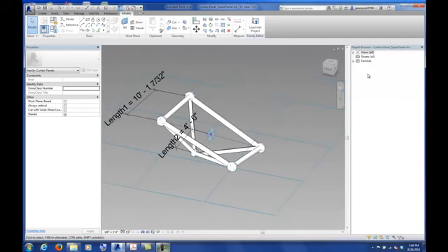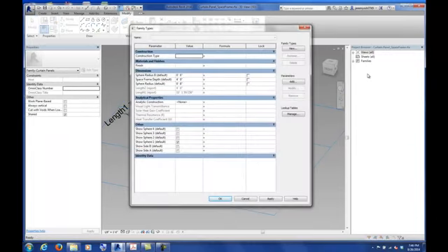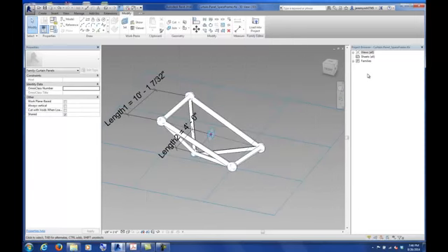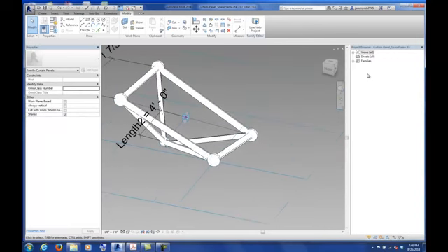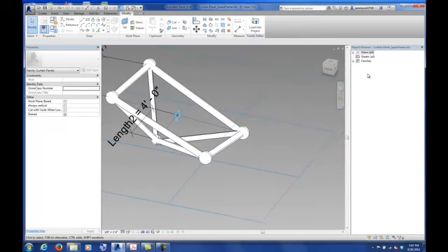Yes? When I try to change that sphere radius, it says can't make type sphere character. Right, so that's the same error I got. You need to go into family types, and where it says sphere radius B, you need to make sure that has a dimension greater than 0. Otherwise, it can't make it. All right, so I'm going to do a couple things here real quick, and then we'll end the class.